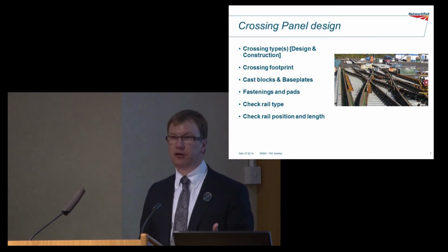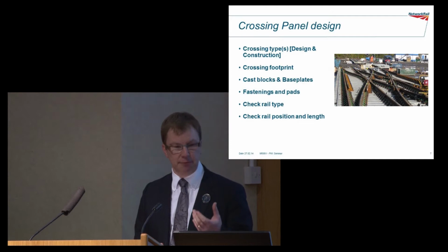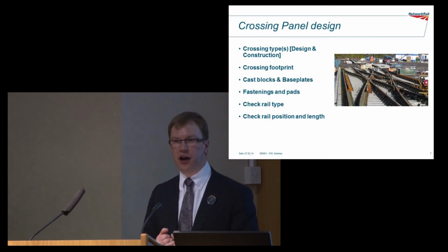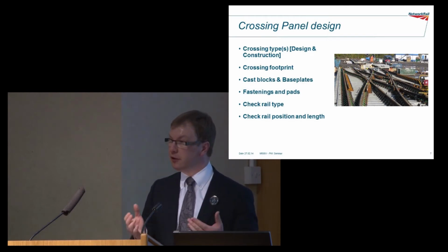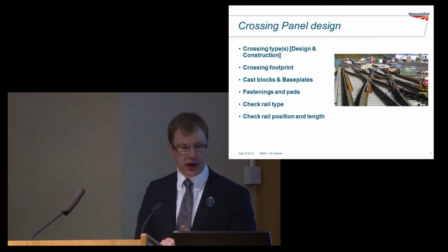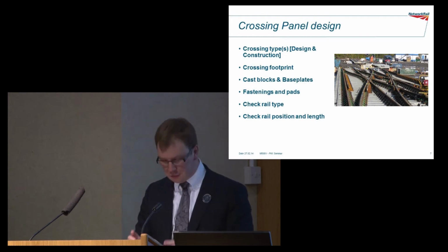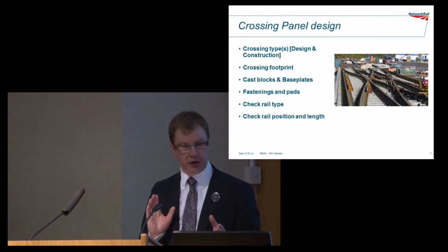Pads are particularly important in the crossing because the impact forces at a wheel transfer within the crossing are about 2.5 times the normal rolling loads. So it's not just designing the pads for normal rolling load, it's designing them to withstand this high impact force in this area. And not forgetting, of course, I'm talking here not just about the crossing but the crossing panel.